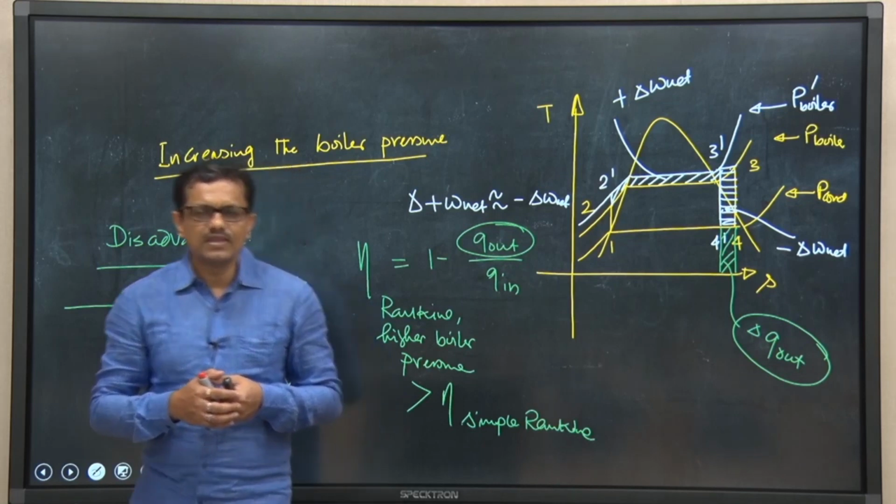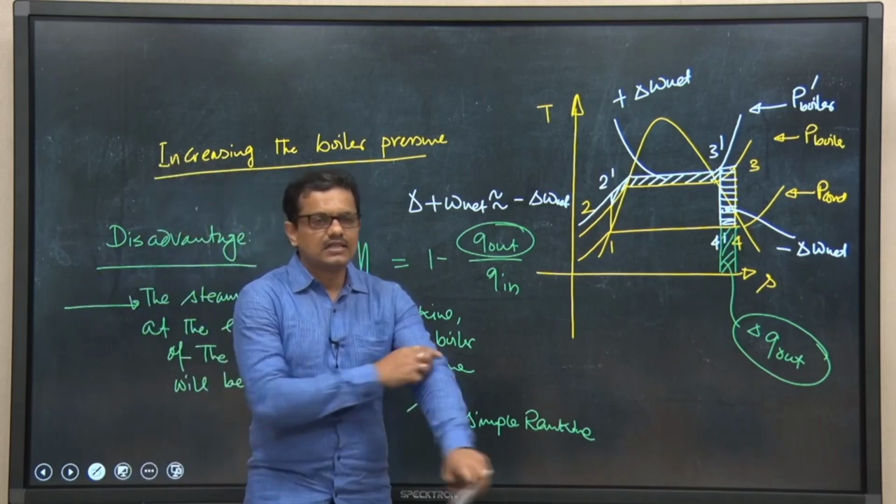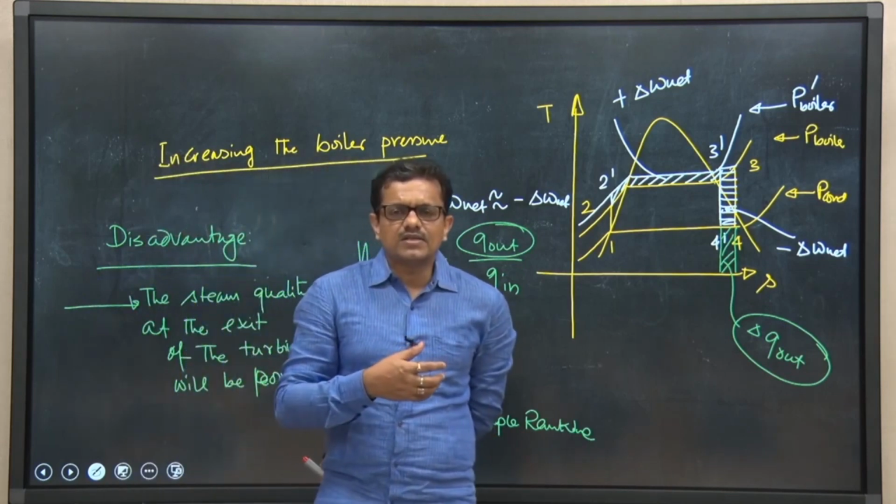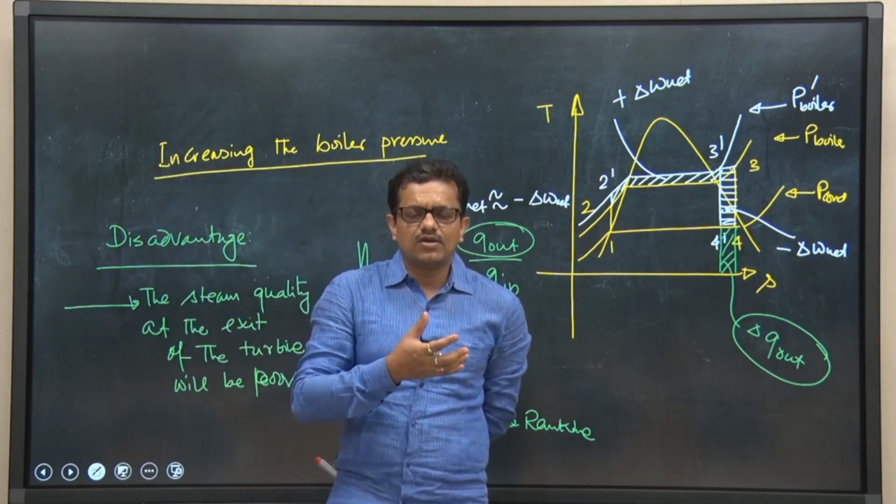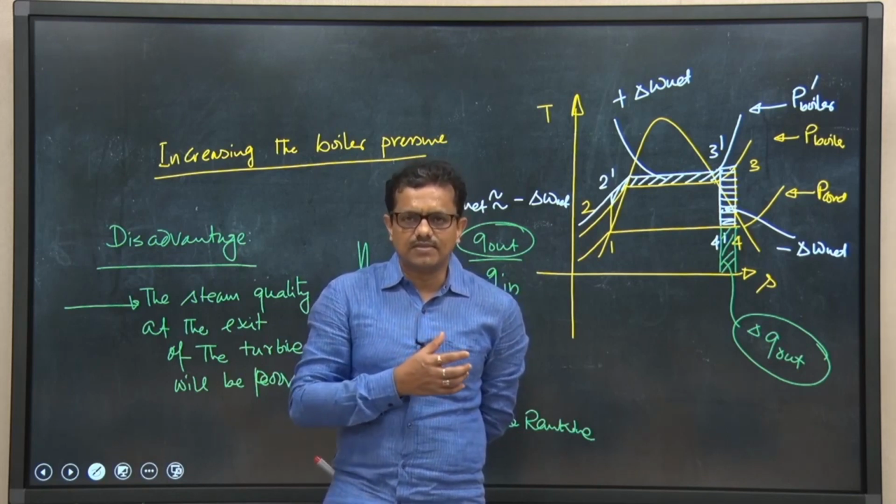Let me tell you again what we have discussed: either lowering the condenser pressure or increasing the boiler pressure, we need to compromise the quality of the steam.